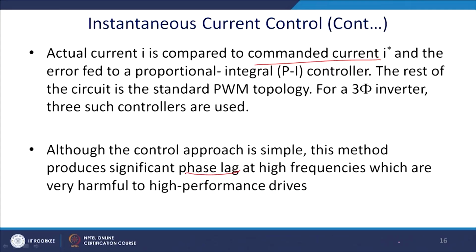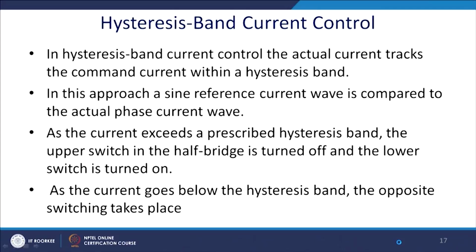At high frequency, this is very harmful for high frequency drives as well as the STATCOM application. So, instead of that we use hysteresis band current control, which is more popular for its simplicity, but there is a disadvantage of it, which will come a little later.